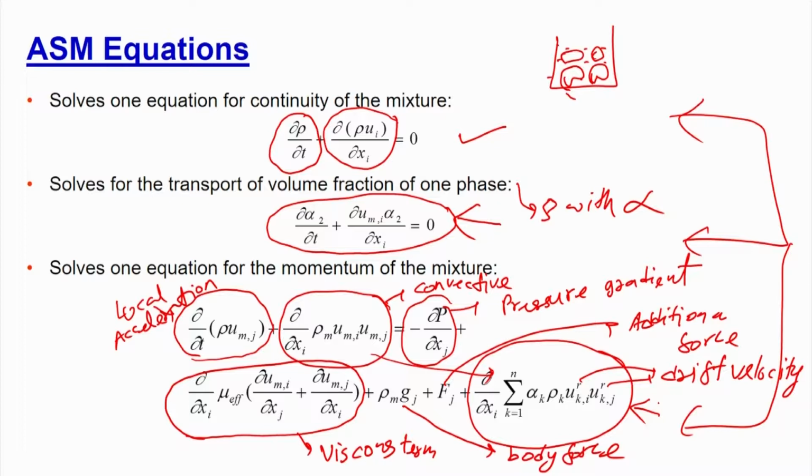And how to calculate it? There are now two more unknowns that you have introduced. One is the mass average mixture velocity. We need to define what this is, and we need to define the drift velocity. So, we have just modified the momentum equation, we have just added one extra term, and the rest of the momentum equation is very close, similar to the single phase flow.